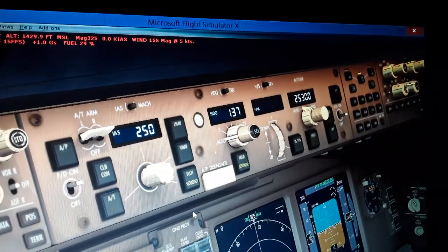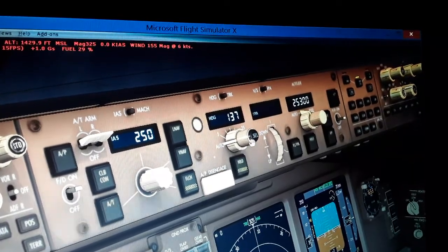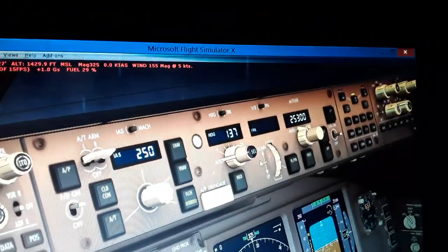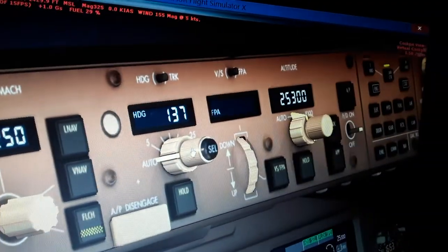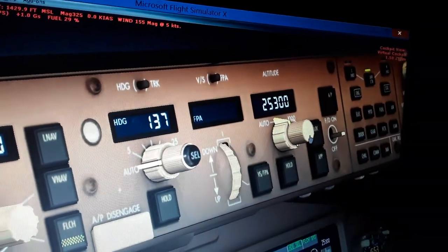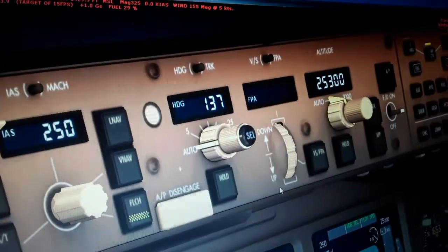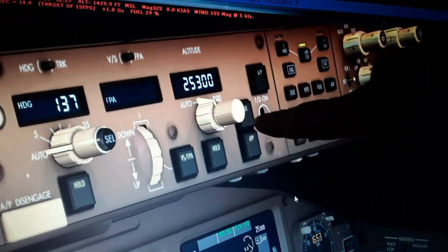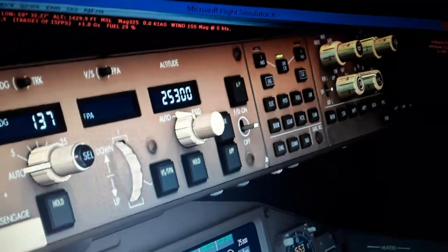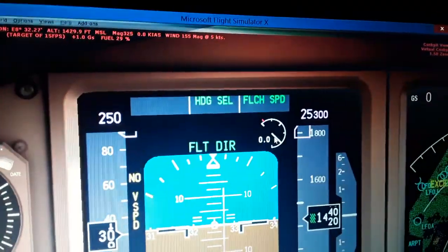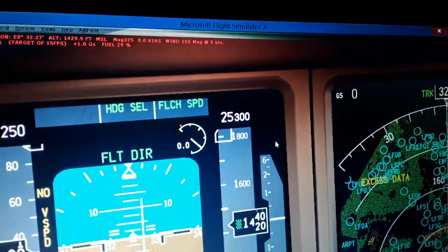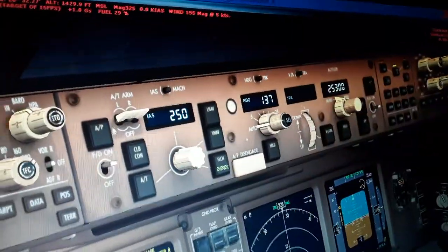We have to select the, maybe this is also depressible. The switch, all of them are depressible. Select through the selector mode. So we have also the VOR localizer and the approach for LSZH, localizer approach mode. A couple more buttons and switches here, so you can see flight director here is engaged. So now we can engage the autopilot here.